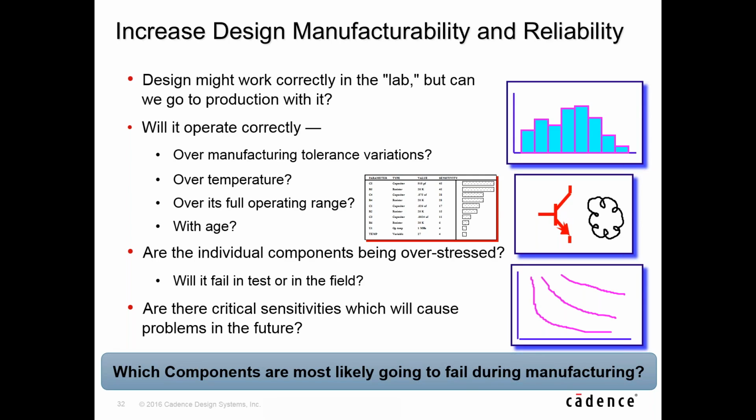But we all know that there are other parameters that are going to vary in that circuit simulation, and that those components, if you were to manufacture 1,000 of those designs, you're not always going to get exactly a 1 kΩ resistor or a 1 picofarad capacitor. Those component values are going to change over temperature, over age, as currents go up and voltages go down. There's going to be all sorts of variability on that circuit. It's not always going to be 100% exactly the values that you have in your design.